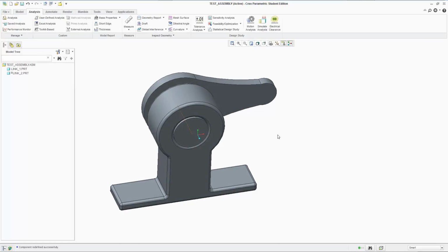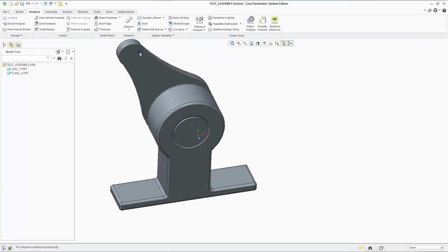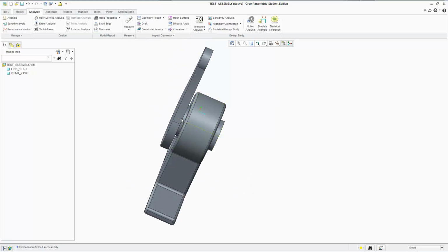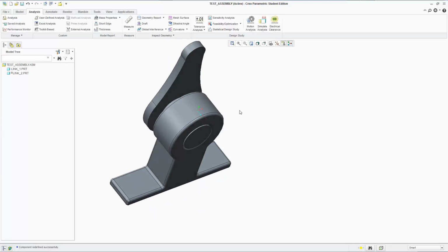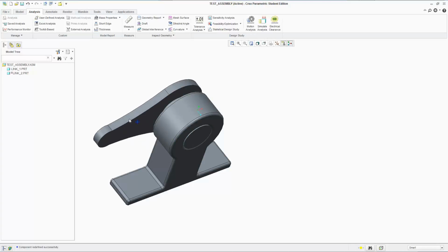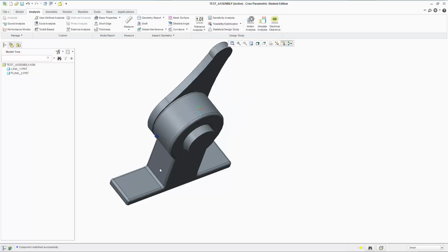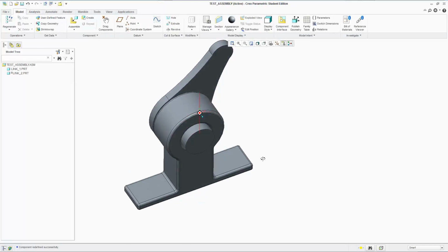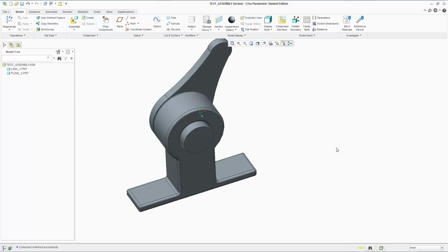So in a cylinder connection, the main difference is it's allowed to rotate. It's allowed to slide back and forth in the limits that we've set for ourselves. So it's only going to slide back and forth in the 0.25 inches, and it's also going to rotate. So just remember, slider: no rotation, we can only slide back and forth. Cylinder: there is rotation and we can slide back and forth. Rigid is just static placement. And I think that's it for this video.